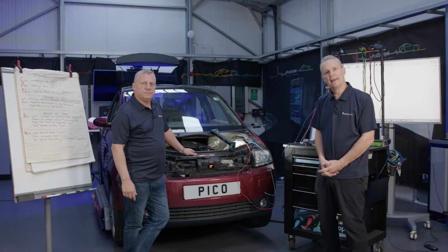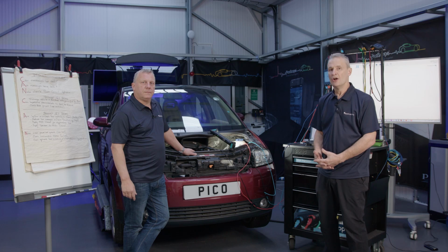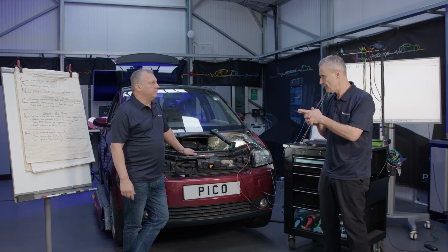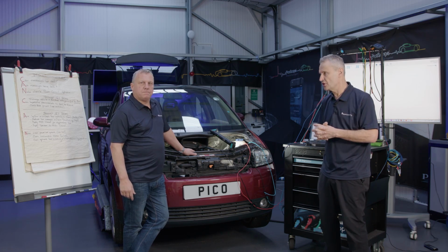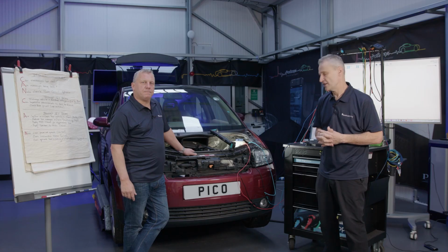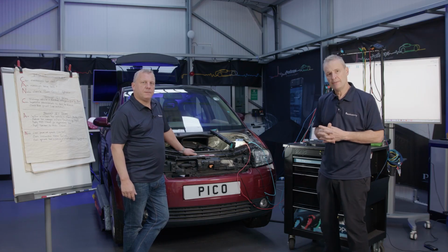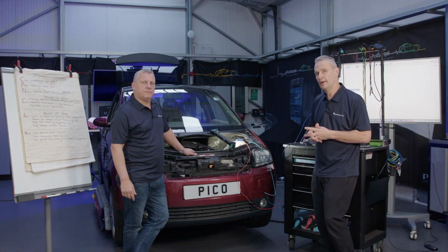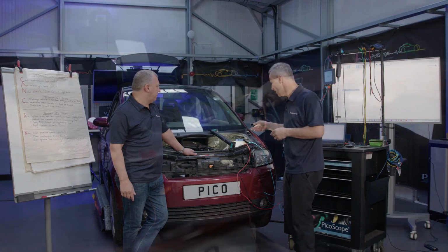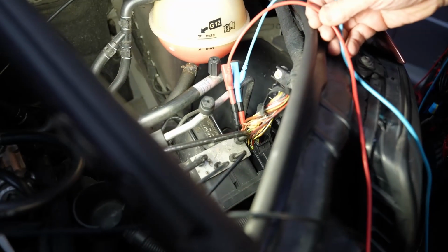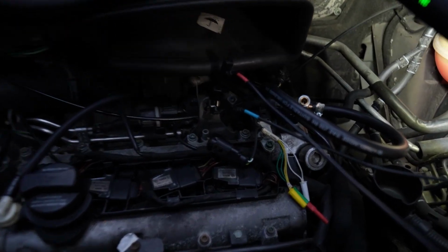Right, so can messages be sent? We're happy with that. So impedance, well, when we say impedance, we're still a bit curious about that, what we thought was a short to ground, but let's see what effect that had on the bus. So can messages be sent? What we're going to do is apply the guided test here. Ben, if you just want to come and see how we're connected, we've just used the ×1 test leads to connect to CAN high and CAN low, and they're both referenced to ground.